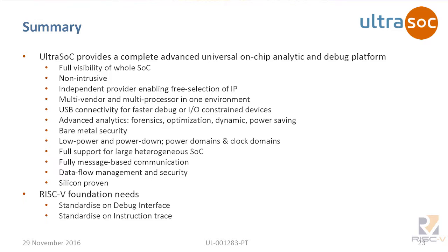We have a novel way of getting in and out of the chip with a USB hub, but we support other routes in and out of the chip as well. It's silicon proven. We have concepts of low power and power domains, so if you have power domains in your chip, we can save state and put state back when you bring the power back online.